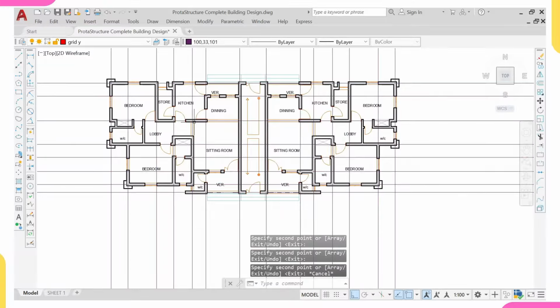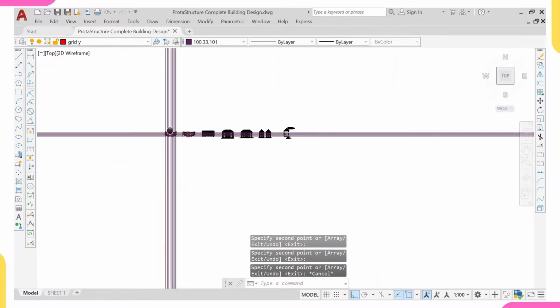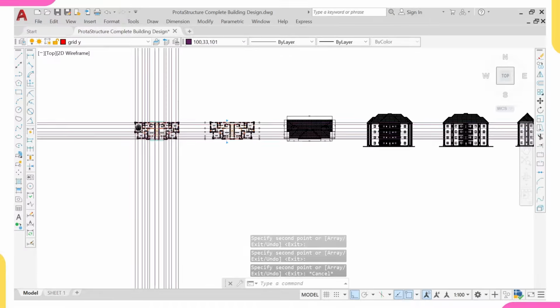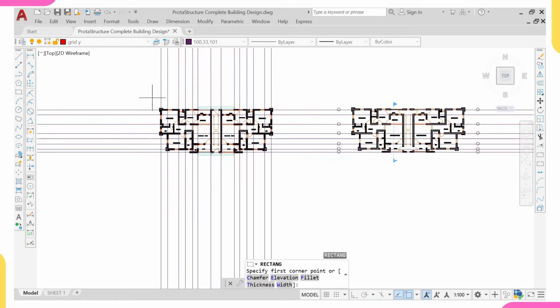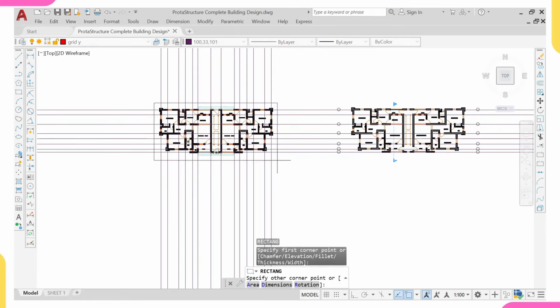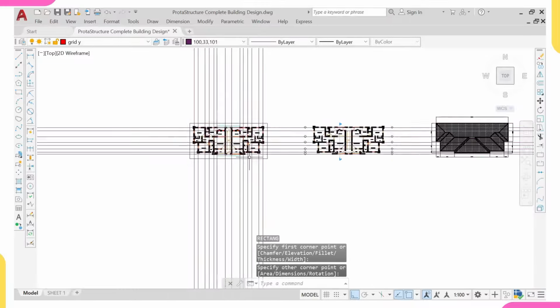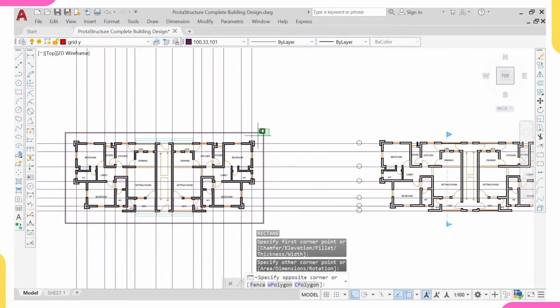So I'll click on escape. Then I'll come over. Like I said before, this is a construction line. So I'll click on left angle. You can just type REC. That's REC, then enter. Then I'll now draw a rectangle around this my architectural plan. So I like to have a rectangle right this. Once I have this, then what I'll do is I'll highlight this rectangle.